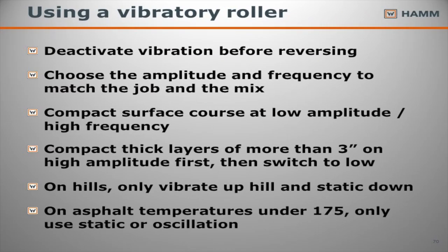When we're using a vibratory roller, we always want to make sure we stop vibration before we go into reverse. I actually ran across a guy up in Canada that kept the vibes on when he went forward and backwards, never shut them off. And he couldn't understand why we had so many bumps in the road.